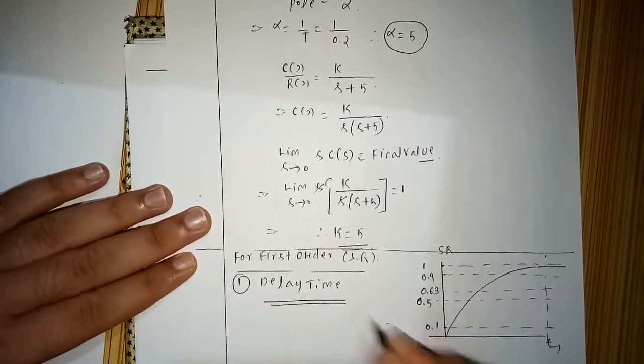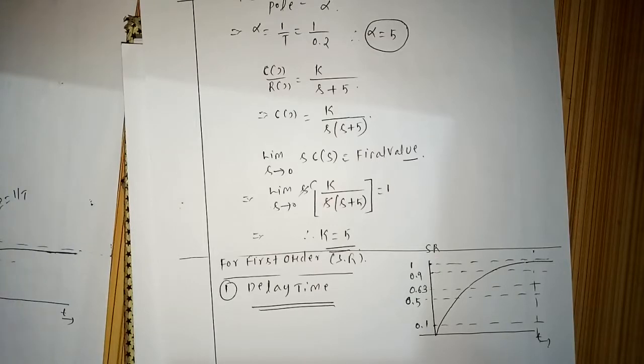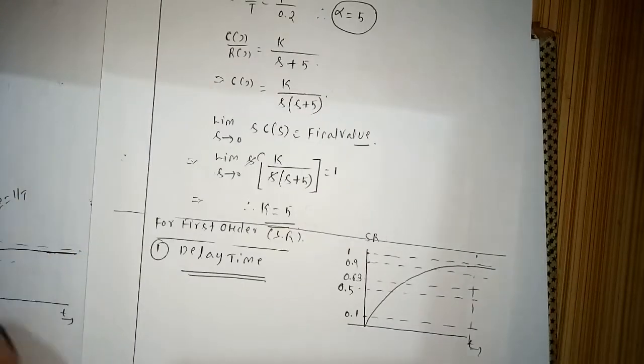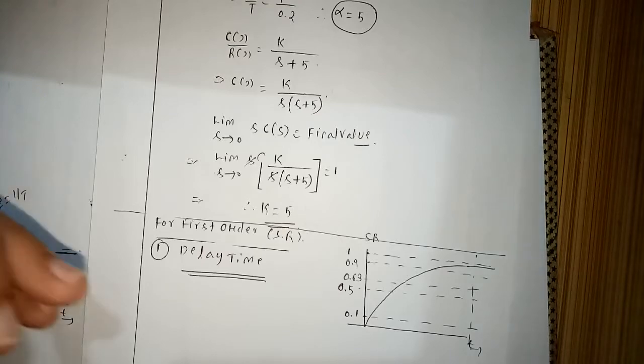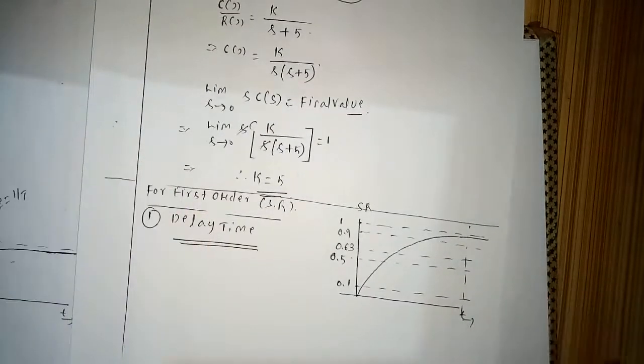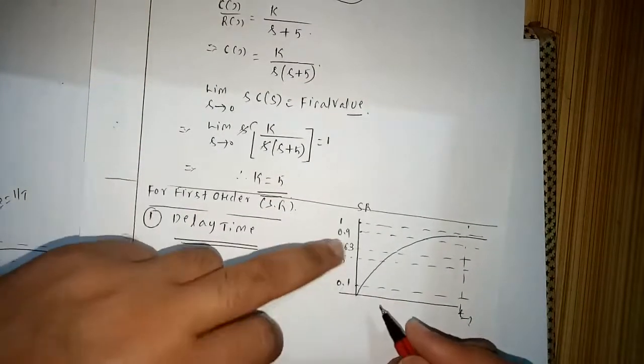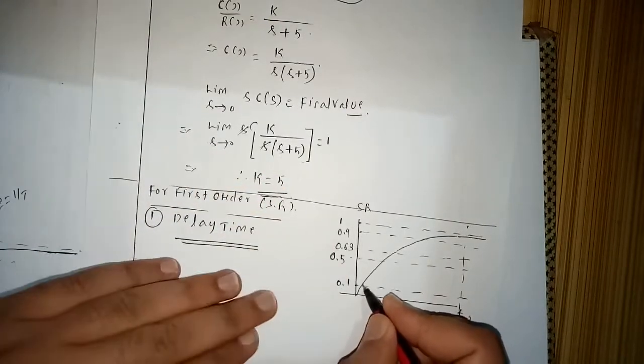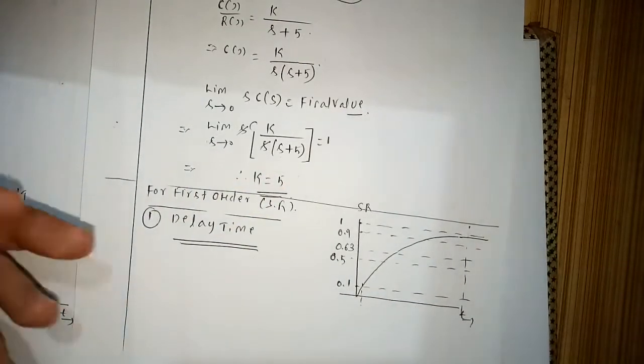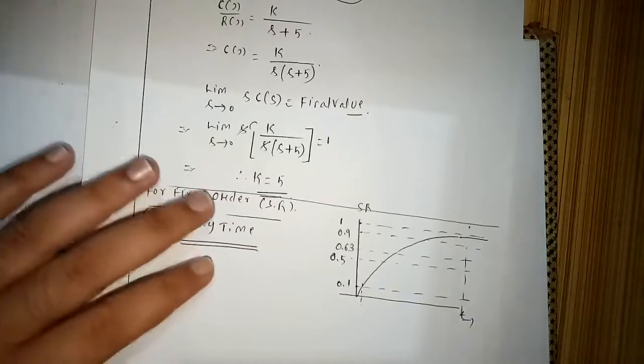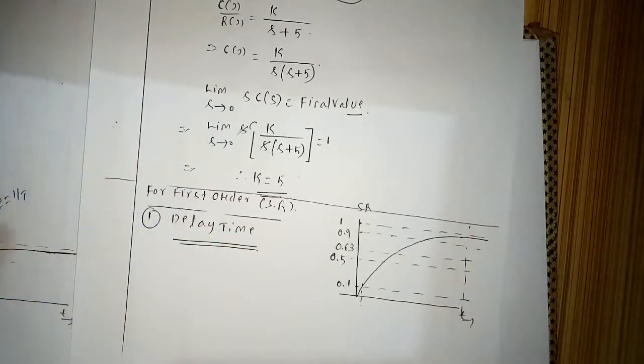Delay time means how much delay the step response is giving before it responds. Generally we take some value, which is not standard, where we can see the effect coming, like 1 is the output, then up to 10%, like 0.1, that is the value when we have started getting a response from the system.